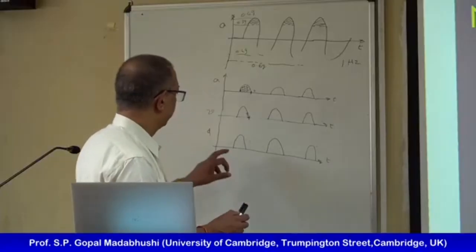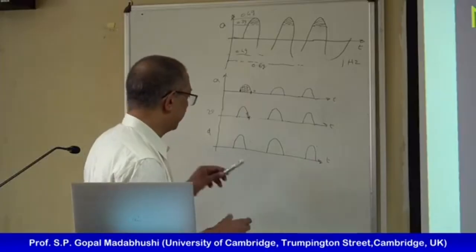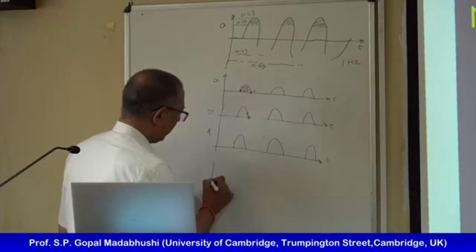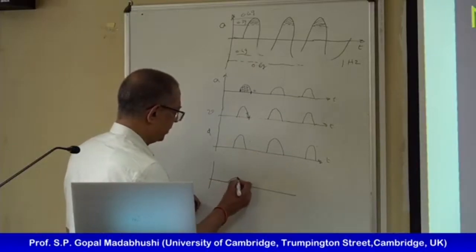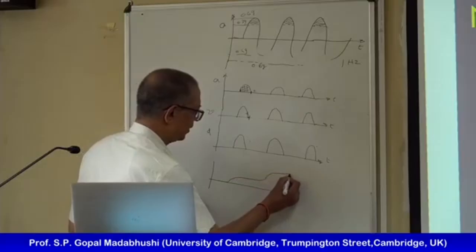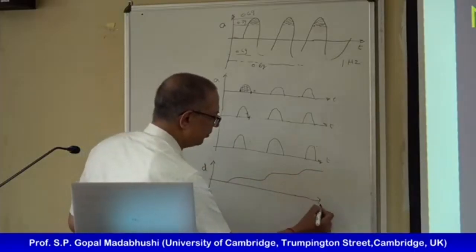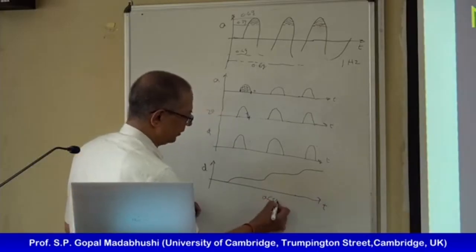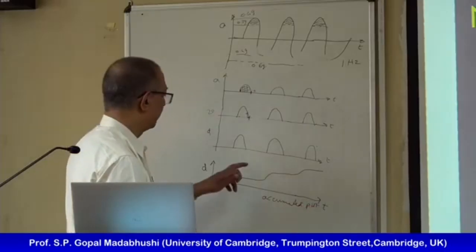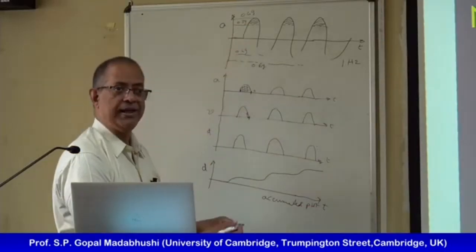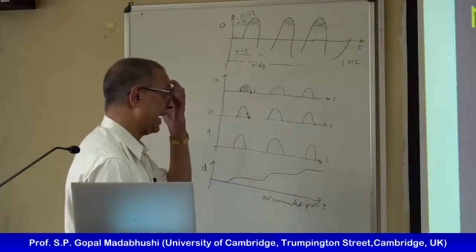Right, so now I can actually plot these displacements. If I were to look at how this will accrue with time, it looks like that. This will be the displacement versus time accumulated plot. Does it make sense? So it will accrue displacements whenever it crosses the threshold acceleration. Yeah? Okay.